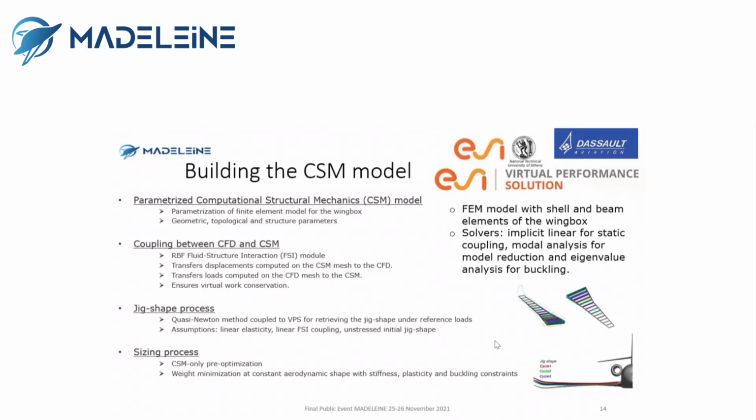At equilibrium, you have a modification of the vertical position, but also a reduction of the twist at the tip. When we do aeroelastic simulation, of course, we have a swept wing, so if you have a flexion, this flexion induces a twist angle modification at the tip and for all the twist law of the wing.